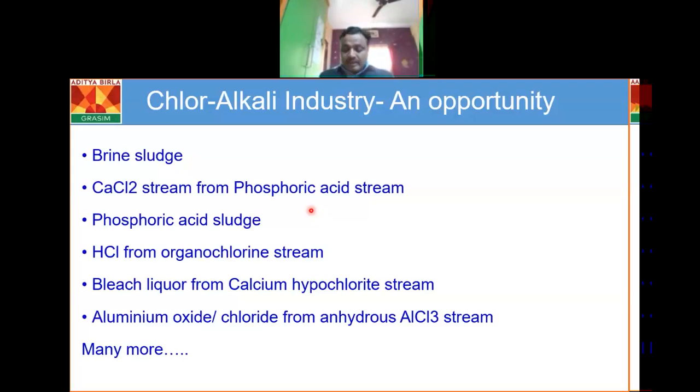But still, if we can work on this stream and reduce the cost of conversion of 15% calcium chloride to granules, where a lot of heat energy is required, this may be a good project for academia. There are directional solvents where these salts can be directly separated out of this stream, which may be a good option.